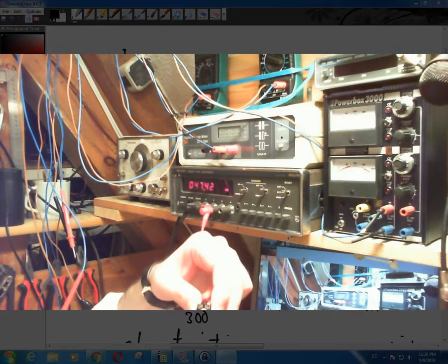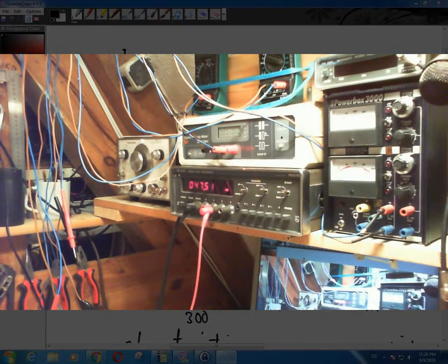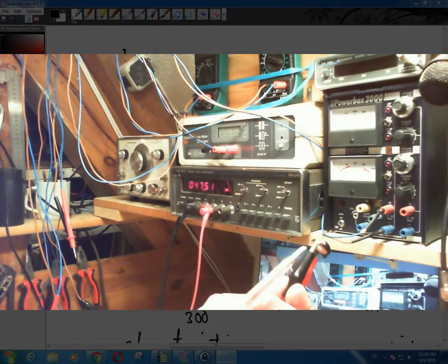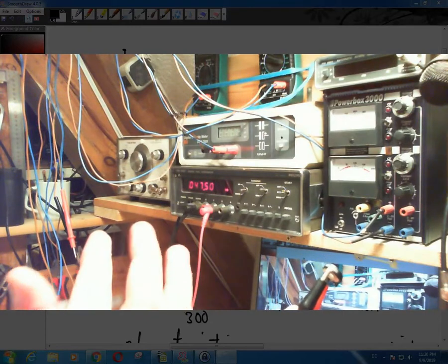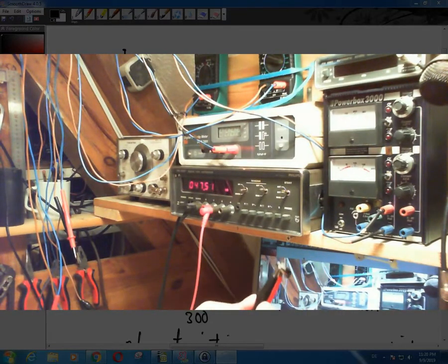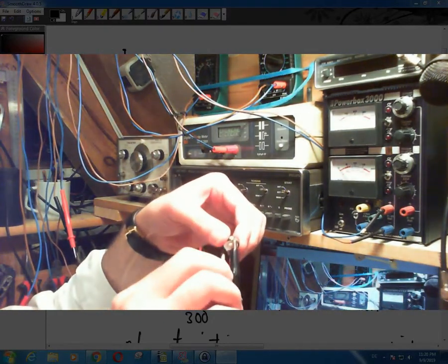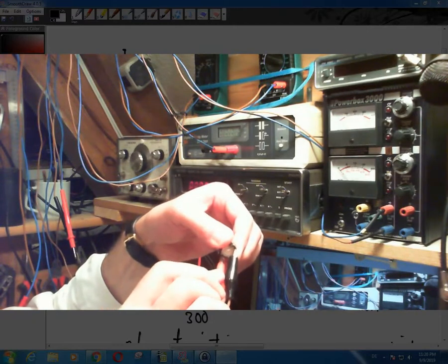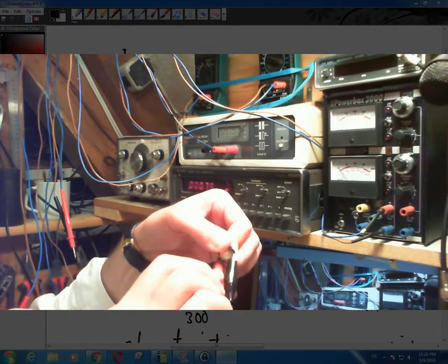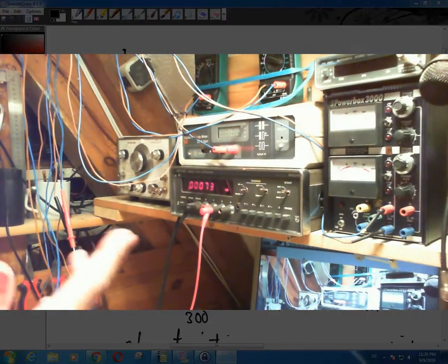And you can see that now the resistance between these two taps, this one and the tap on the left, is 47 kilo. Now the center tap, I keep the center tap and then move this wire to the other lead of the potentiometer, and then we should see 0 over there, or something like 0.7 ohms.